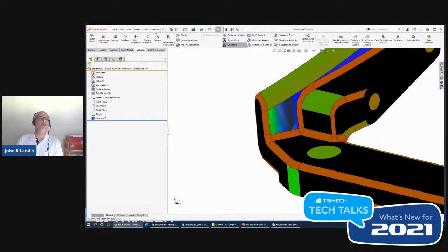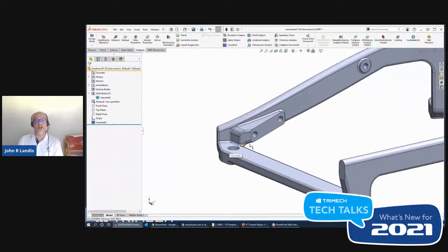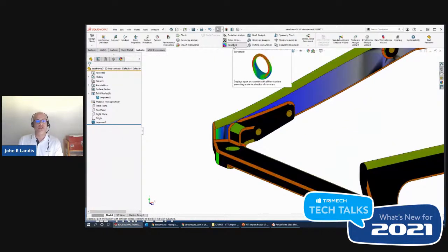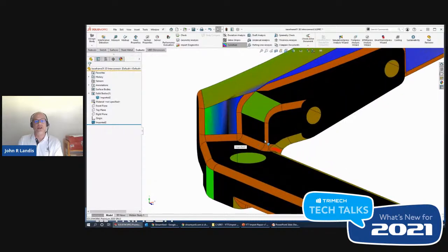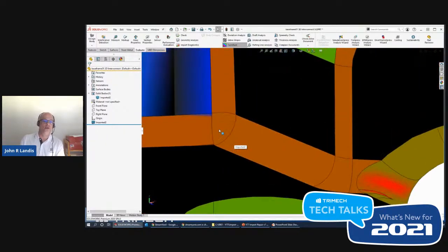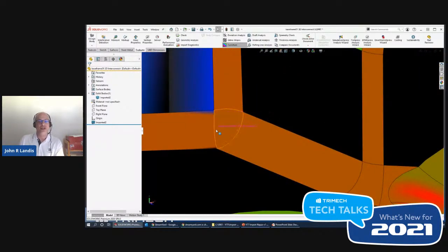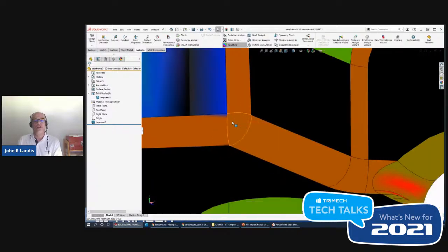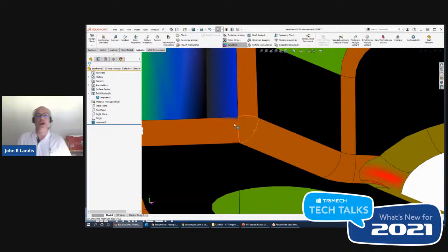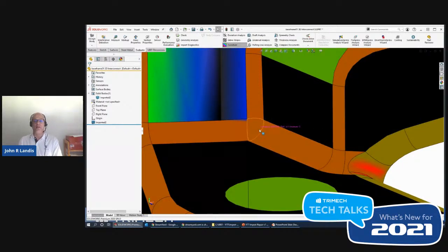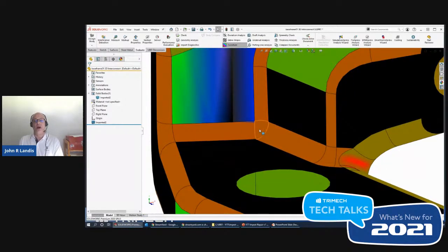As a point of contrast, when I flip over to the other model that I brought in via 3D Interconnect, and I turn on the curvature display, I want you to notice that the profile of this 3-sided patch is consistent, and we don't see that little divot like we did before. So we've basically been able to illustrate where we have a defect in the topology of our model, as well as the contrast that is evident because of the way we brought the imported model in.